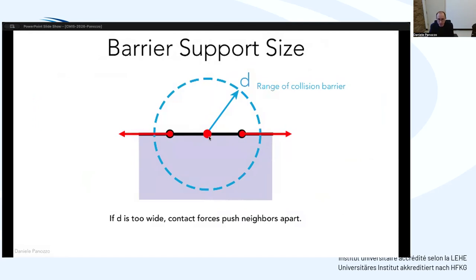So how do you distinguish these? There are a bunch of approaches. The two more common ones are to either ignore some part of your discretization around it, like a one-ring. But as you can imagine, this leads to incountable trouble in trying to prove anything or showing convergence and so on. The other more common option is to try to use normals to distinguish if it's itself or another surface.